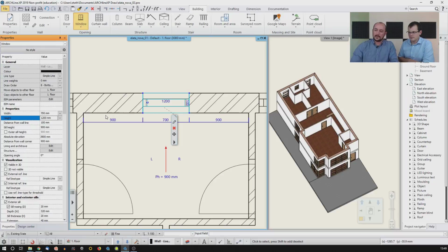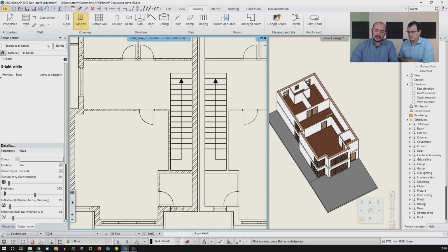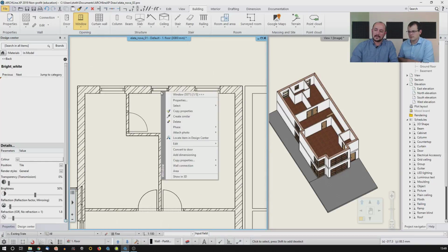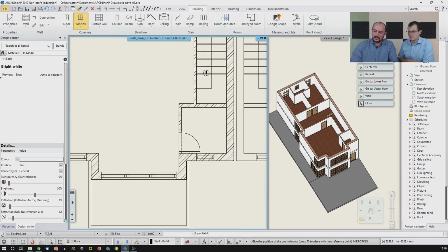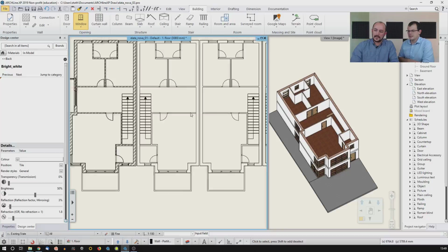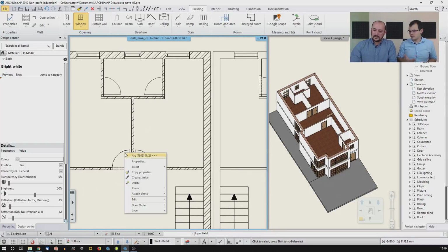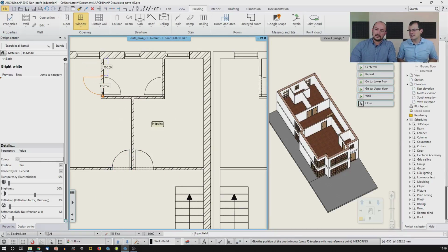So now we have a perfect window appearing over there. And now, because this window and this window are similar, it is the perfect time to use, again, the right-click window, create similar tool, and go back here and find and match to the original drawing. And now we are done with that design. I think there are just 2 doors missing up there, so maybe we can again use the same create similar tool and just place them over there, because I assume they are of the same size, so shouldn't be any problem with that. So that's why it's always good to review your work, because sometimes the line drawing takes away your focus.